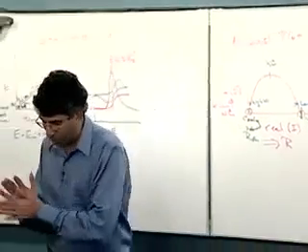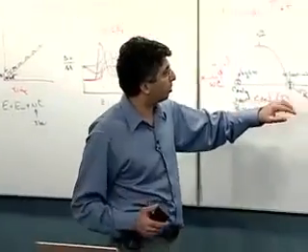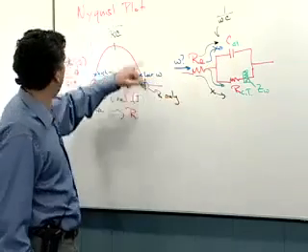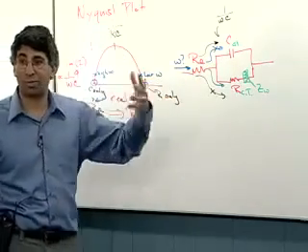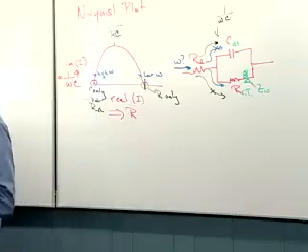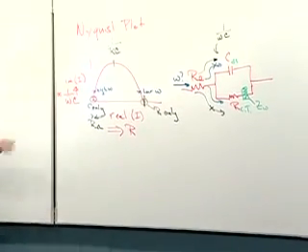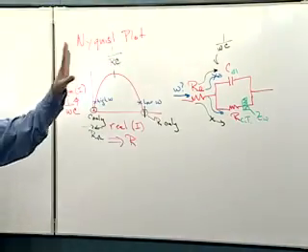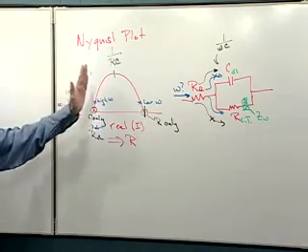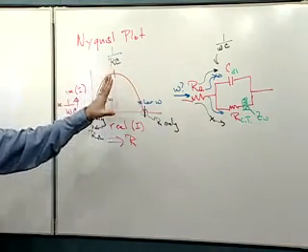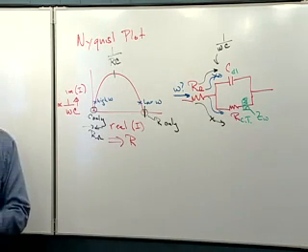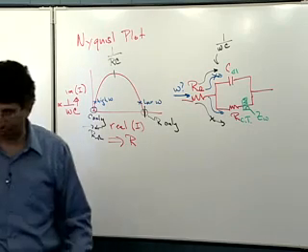And so, since the thickness will change the resistance of the interface as well as the capacitance, where the semicircle falls will tell you about the thickness of the corrosion layer. And so you can do some calibration curves. You don't even have to work out specific details. It's not important what the resistance and the capacitance is, but you just need a calibration curve that shows you how this semicircle shifts as the corroding layer gets thicker. And so you can monitor a corrosion rate by doing this, by monitoring this over a period of time.